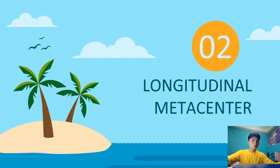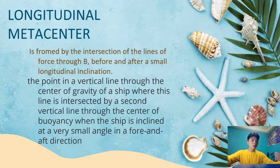Number 2 is the longitudinal metacenter. The longitudinal metacenter is formed by the intersection of lines drawn through the B before and after a small longitudinal inclination. It is the point where the vertical line through the center of gravity of a ship is intersected by a second vertical line through the center of buoyancy when the ship is inclined at a very small angle in the fore and aft direction.